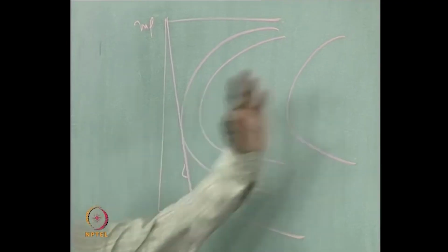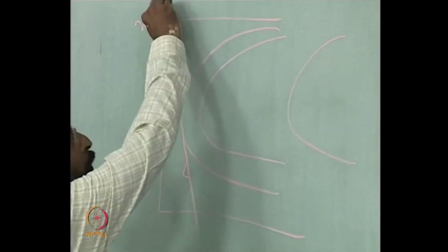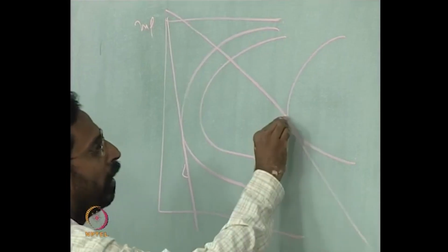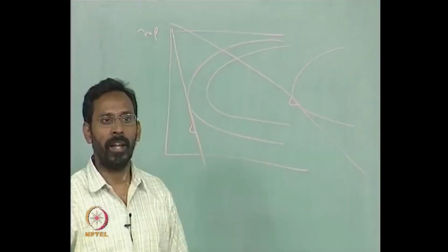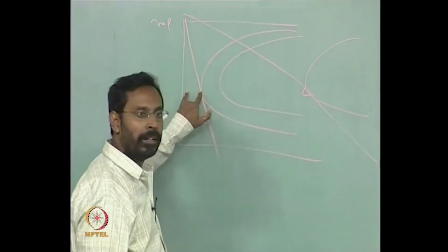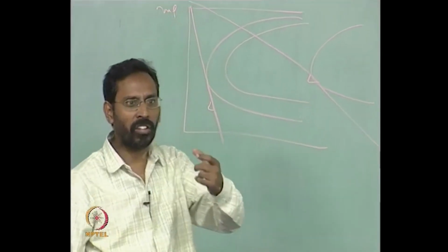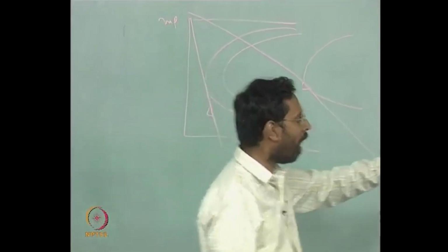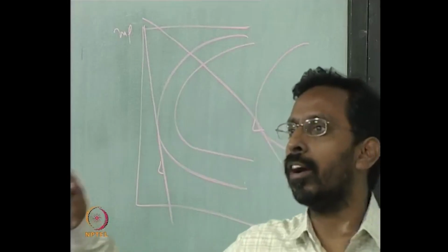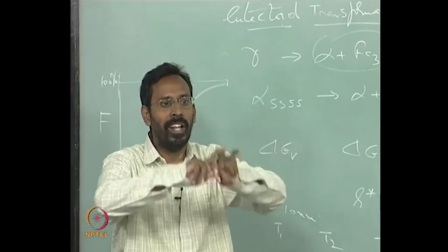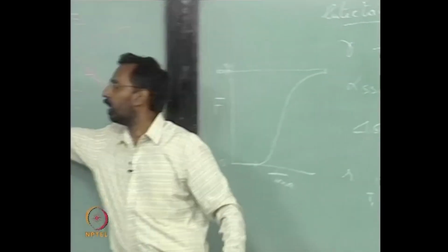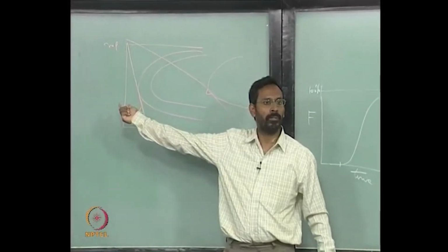The C curve is shifted so much to the right that you need a very slow cooling rate for it to become a glass. So, it is that diffusion and the structure formation, basically it is the R star and the D combination that will decide what is the critical cooling rate that you need to adopt.